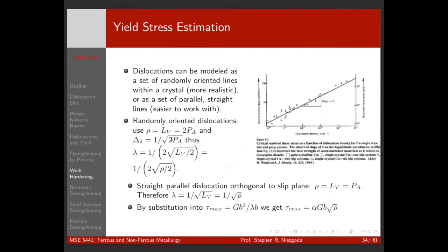And there are mathematical principles like this that we can use to do things like, how do I know a 3-dimensional grain size distribution from a 2D section through my sample? I need to be able to prove rigorously that if I take the areas of all my 2D grains, it's going to relate to my volume distribution for 3D grains.